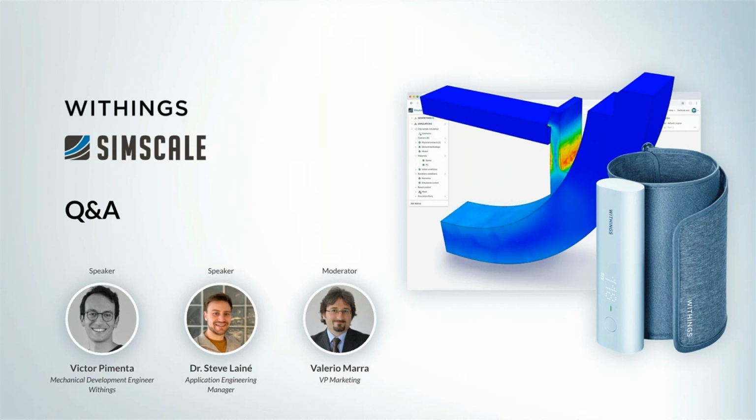We typically do this by about 5 to 10 at a time, until you get to the point where, when you post-process it, you don't see significant penetration, and you know that you've got a nicely converged result with the correct penalty coefficient. Thank you, Steve. That makes sense. Otherwise, all the forces and other parameters are going to be off.